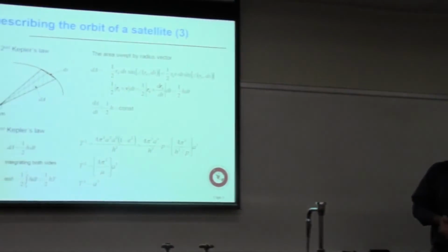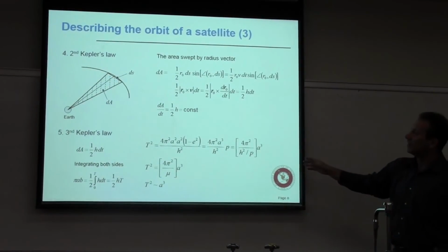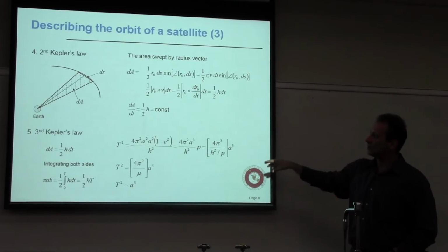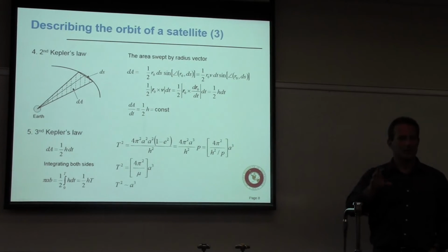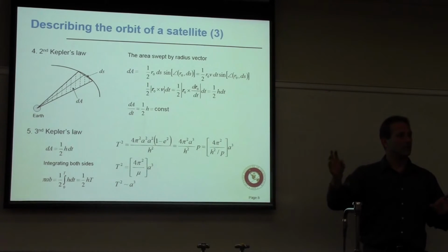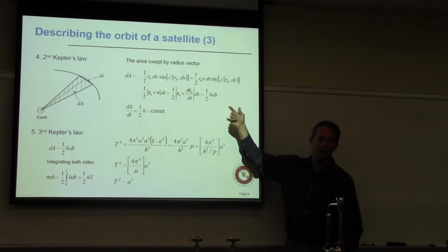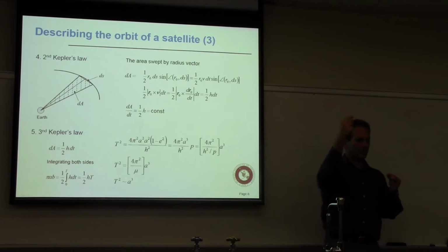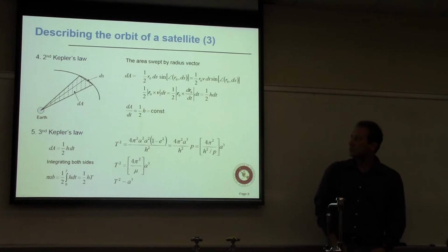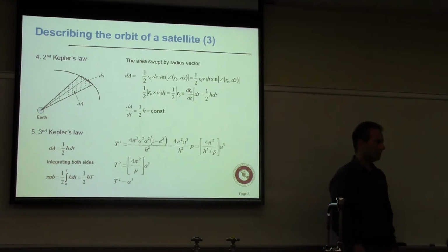elliptical coordinate systems. Because one thing that you probably notice, all of these equations here give us just the geometrical relationships. There is t missing from all of these equations except maybe this one here. So you know the path, right? But the velocity of the satellite changes on the path. Remember, it's faster around perigee and slower around the apogee. So it's relatively complicated to calculate the position of the satellite if you try to follow the differential equations on their own.